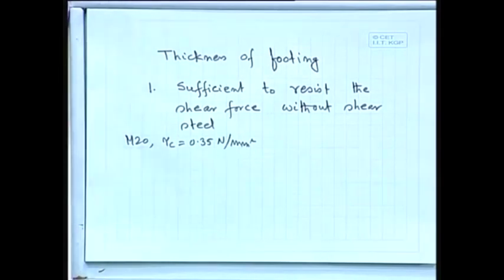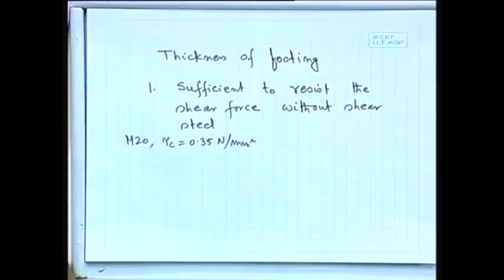The critical one, let us check it, yes, sorry, that is say 0.28. But 0.28 is the minimum as per table 19 of IS 456. If we know the area of tensile steel, depending on that we can take say 0.35. That's why I have told 0.35.